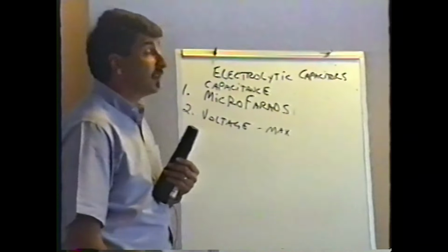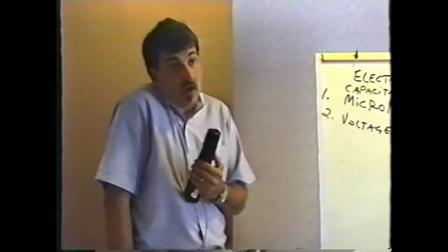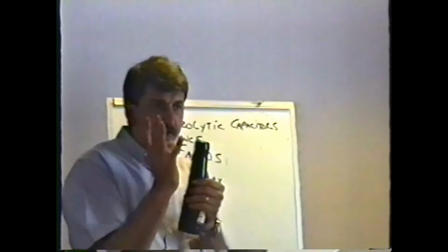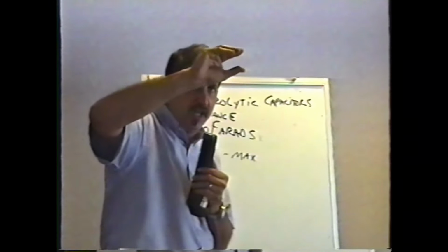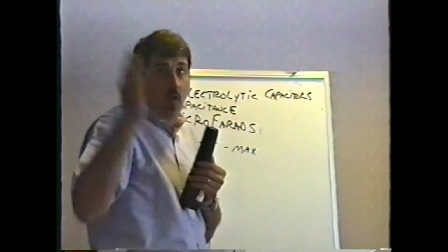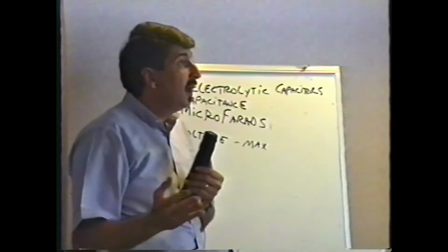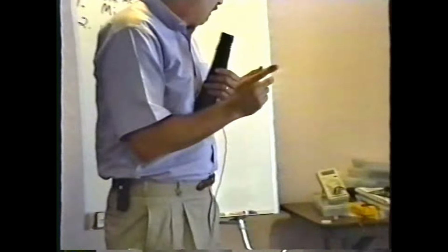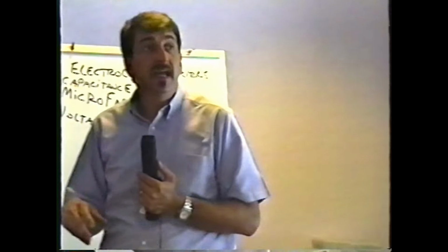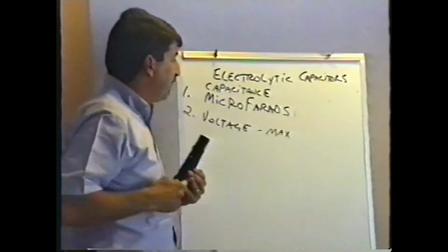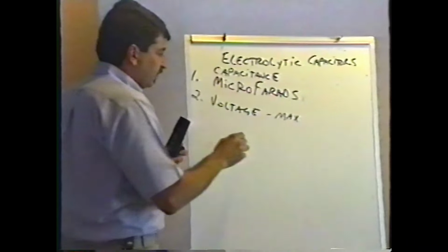Now, depending on what the circuit is that it's in, you'll see all kinds of different symptoms. In a monitor, it causes everything from a distorted picture, where you've probably seen this, where the picture is shrunken down at the top, squished at the top, and stretched at the bottom, or the sides of the picture are curvy, it just looks distorted. Those are capacitor failures. In a power supply, we'll see that there's lots of capacitor failures, and it causes everything from a power supply that just doesn't work at all to a power supply that creates all kinds of strange electrical noise.